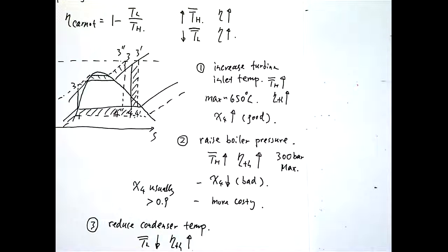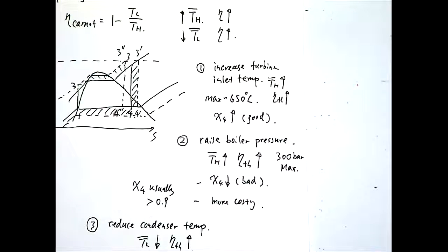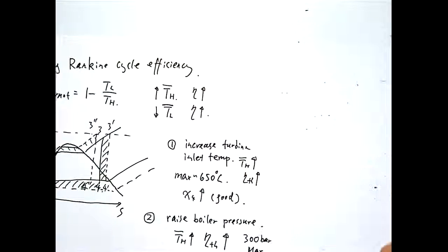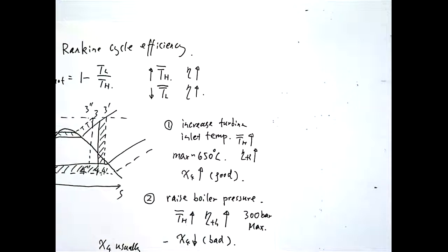If you remember the critical condition for water we mentioned before, the critical point is 220 bar in terms of pressure and 374 degrees C in terms of temperature. So if you look at these two conditions together, the maximum temperature and maximum pressure are both higher than the critical point, which means many modern steam power plants actually operate with supercritical water.